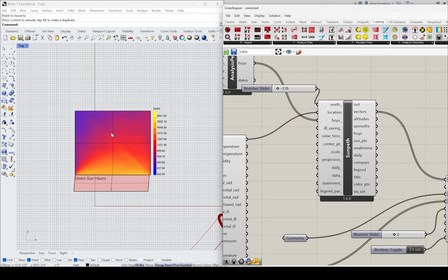So this could be a way to look at a floor, like you have a facade that's big in glass, and you have this big floor space, and you want to put some shading devices on it. If you get it the right direction, you can model the shade. You can model that floor and the general walls around it. Just leave whatever place is a window or glass. Don't put anything there, and then model your potential shading system and look at different types of shading systems, right?